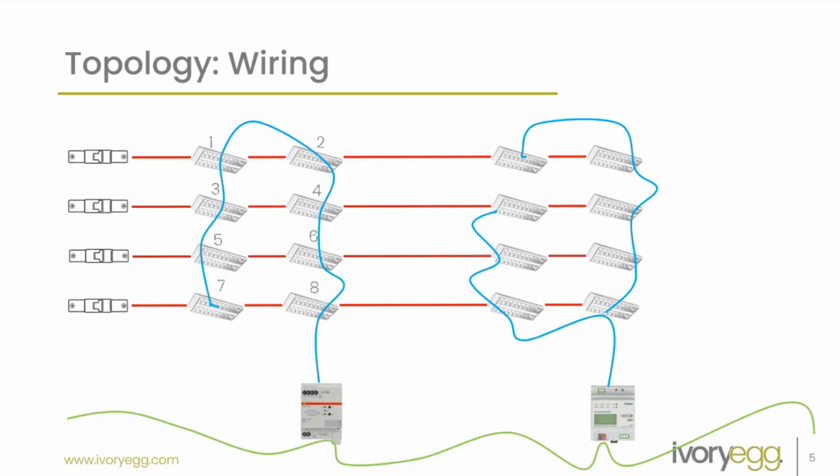What we do then is simply we give every fitting an address. The Dali addresses can go anywhere from 0 up to 63, or as we know it, 1 through to 64. So the maximum number of fittings you can have on one Dali network is 64 fittings. And we'll talk a little bit more about how many fittings we really should put on there. And we address the fittings on the second network. Okay, so this is where it gets interesting, and this is the part that makes the flexibility, and you can see why I have office blocks that can change their configuration depending on where they want to group their fittings.